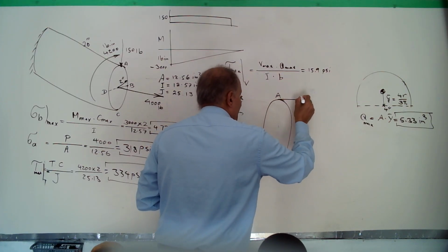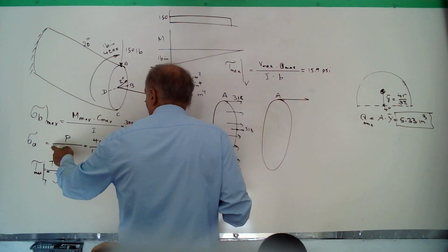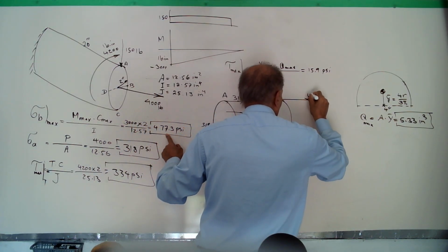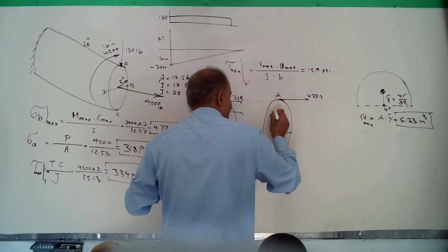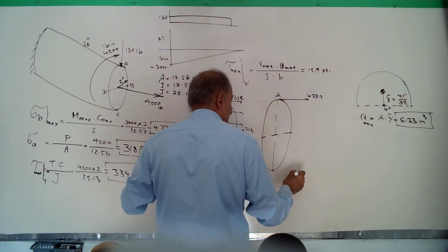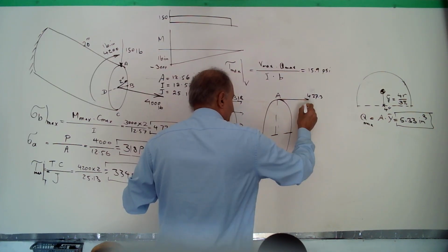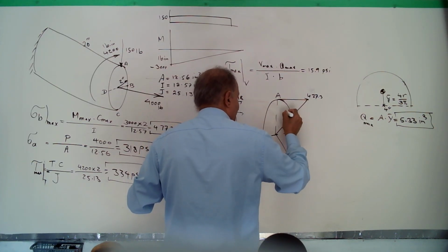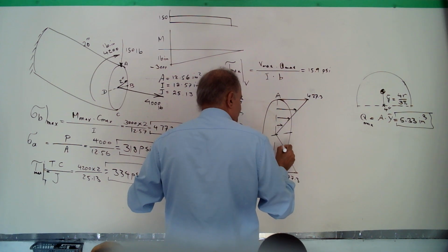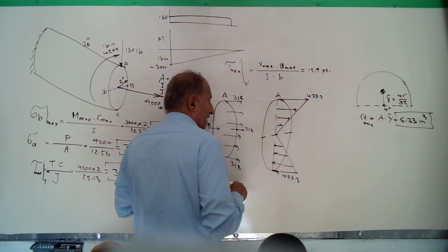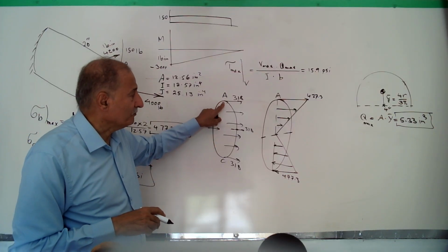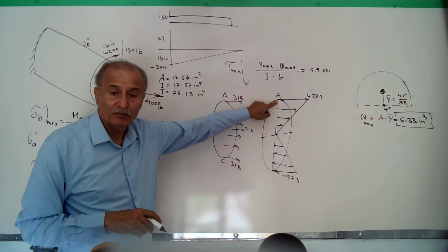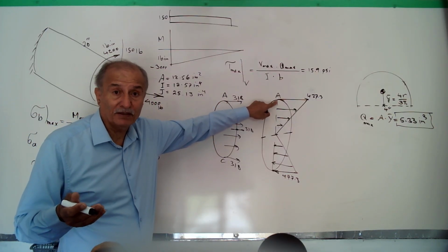At point A, it is equal to 477.3. That's the neutral axis here. Compressive 477.3, and then it changes linearly with respect to the axis. If you add them together, you add them point to point. For example, point A for axial to point A for bending, because it's the same place where the stresses happen.